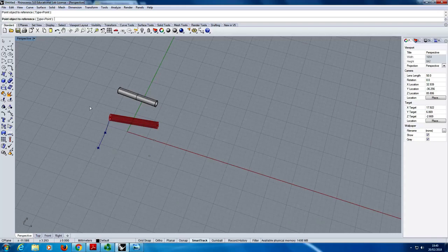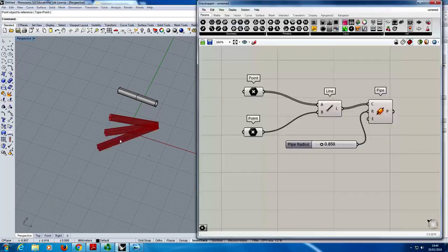And as you're drawing this out, it will draw these blue lines behind it so you can see what points you've selected and in what order. And the order can be important, as we'll come on to in a minute. So select those 3 points on the left-hand side, and then once you've done that, either right-click or hit return, and then that will end that selection.